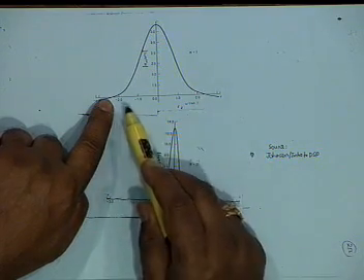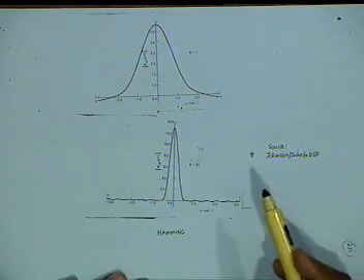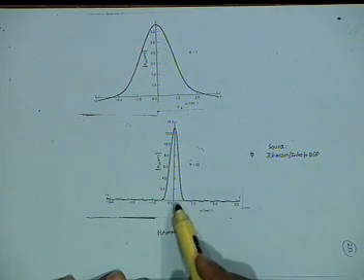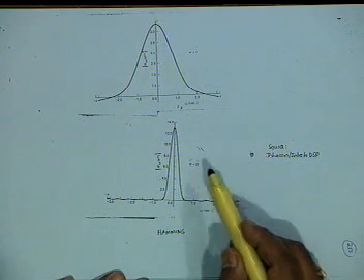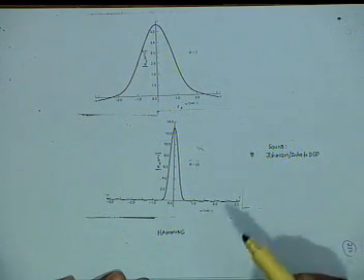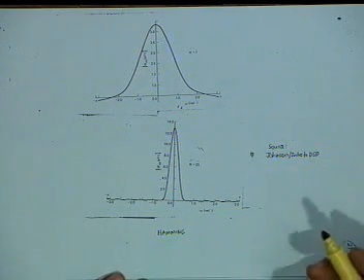It can be decreased to approximately 1 if you raise the length to 25, but then the side lobe height also increases. So it's always a compromise between main lobe width and side lobe height. Whatever is acceptable to you, you try the windows, and you use that.